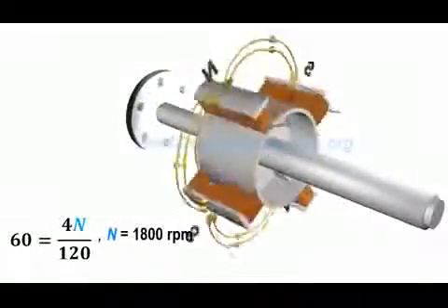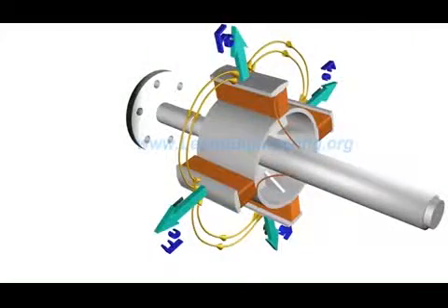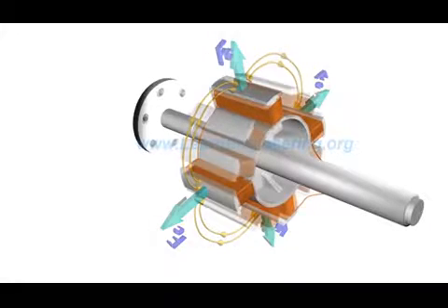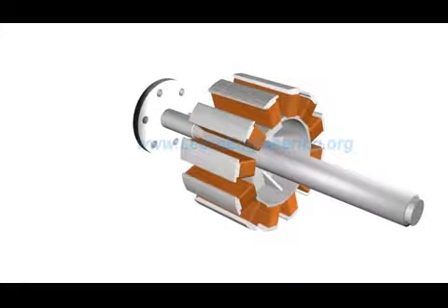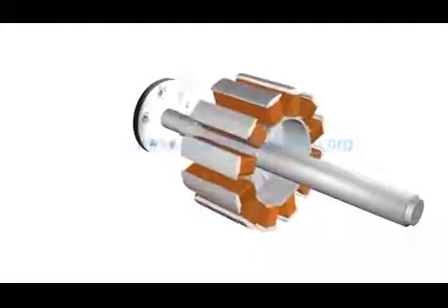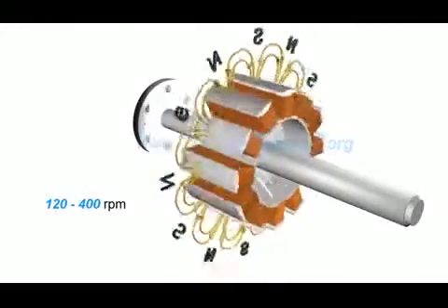Such huge RPM will induce a tremendous centrifugal force on poles of the rotor, and it may fail mechanically over time. So salient pole rotors generally have 10 to 20 poles, which demands lower RPM. Or salient pole rotors are used when the prime mover rotates at relatively lower RPM.